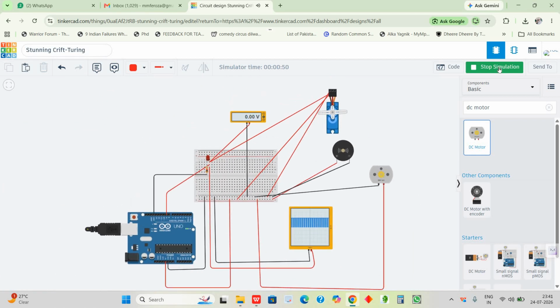So this is how you can connect all the elements for the PWM signal. Here what we have done, we have taken 4 output elements, that is 4 actuators: LED, servo motor, DC motor and buzzer. You can connect other elements also. And this is a multimeter, this is an oscilloscope, and this is the small breadboard, LED, and one resistor you have to choose. So this is about the PWM experiment using Tinkercad.